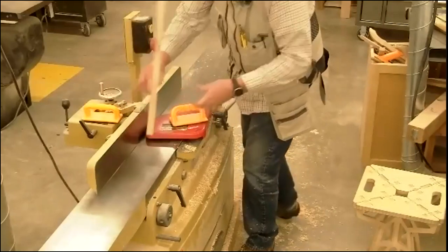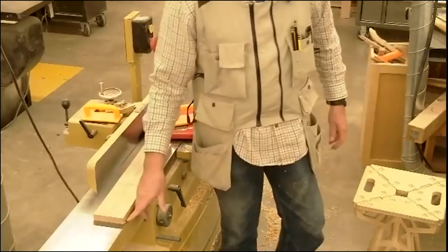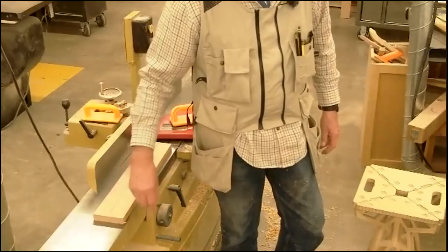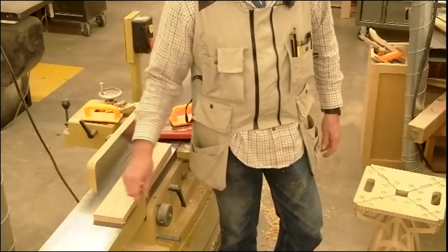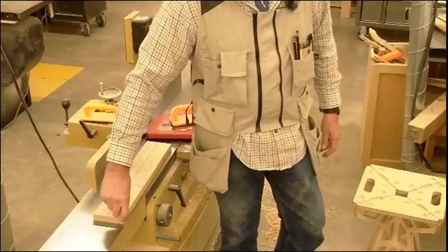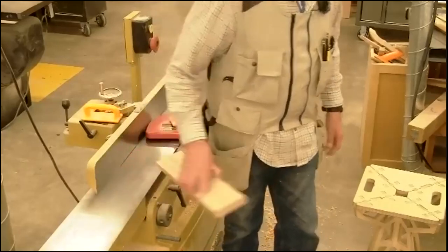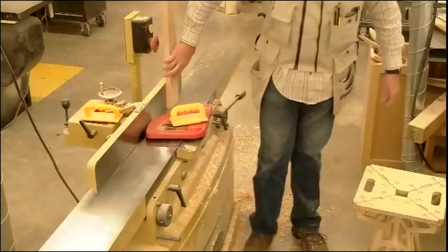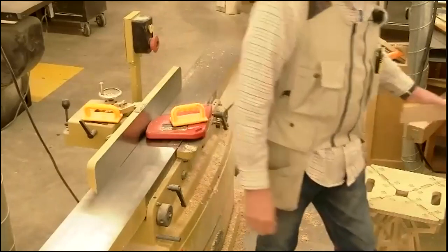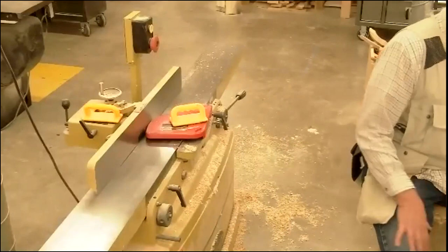Not real bad. But you can kind of see where the end of this board exited the joiner, there's some tear out. It splintered and took a chunk out. I've seen it take big giant chunks out of there before. But when we're doing that to end grain, you're taking a very good chance of ruining the corner of the board as it exits the cutter head. Okay. So first of all, it's not 12 inches contact with the fence and table, and it's end grain. We don't joint end grain. Okay. So material's got to be 12 inches long. We don't joint end grain.